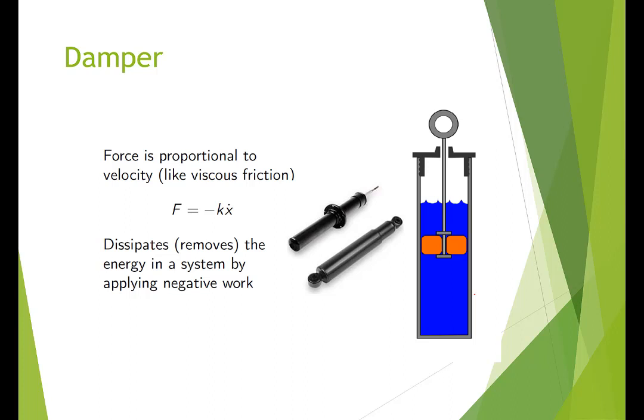Suddenly, as it moves fast, it tries to push it back down to where the spring initially is. A damper is similar, but it absorbs kinetic energy. It applies a force proportional to the velocity. So if something is moving too fast, the damper makes sure it moves slowly and potentially brings it to zero velocity. That's why springs and dampers are used a lot in suspension systems.